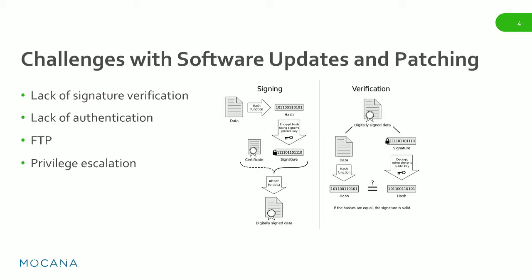Right, so the first challenge obviously is the payload has to be verified for authenticity, which has typically been done through a code signing mechanism, but with the caveat that the certificate cannot be validated, since a lot of these systems may not have connectivity to the internet. That also causes a problem of not being able to authenticate the device before giving the information to the device, especially if you're doing a pull over the air or over the wire.